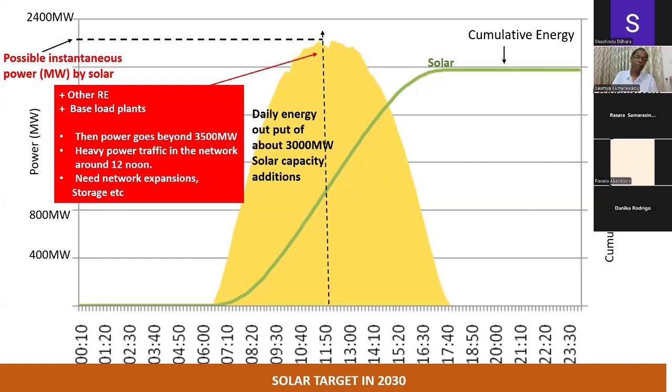And also to maintain the system inertia, primary regulation and secondary regulation, we should have some firm energy power plants as well. With all these, the peak value will go up to about 3,500 megawatts. But you know that the maximum demand of our system at night time is also about 2,800 megawatts. In daytime, it is less than that.